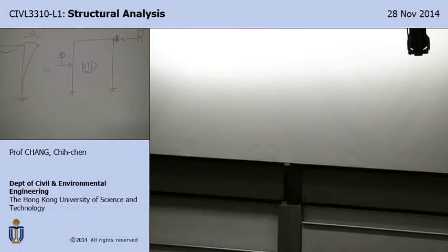So you can do a moment distribution calculation, assuming you have a deflection, and then calculate how much force is required. So after you've done that, you compare this result and that result. So now you have this value, and you have that value from the first calculation. So you just take all the values here and multiply by the coefficient R over Q.